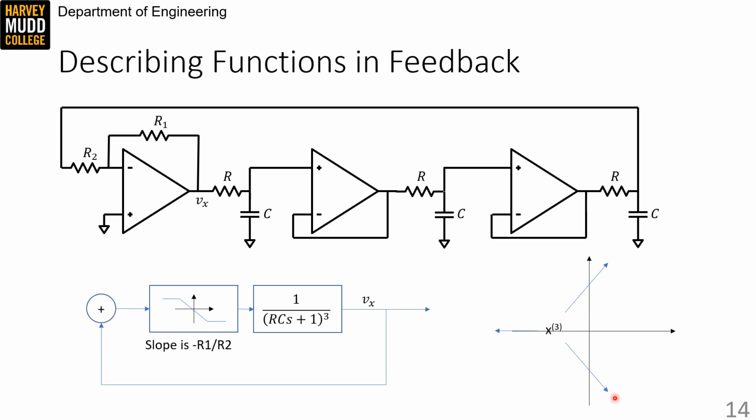And poles in the right half plane will cause that input signal to start increasing exponentially. So as the amplitude of this unstable system increases towards the rails of our describing function, then the describing function will shrink, and the poles will get pulled back towards the j omega axis.